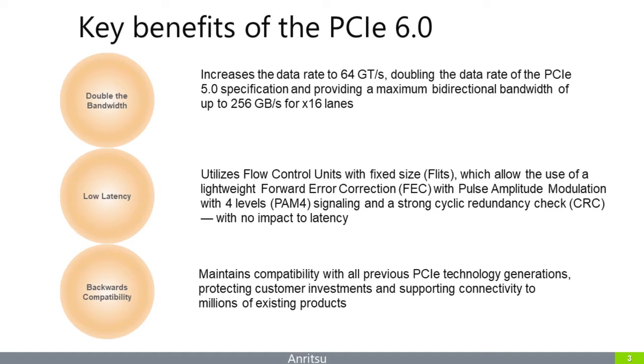Compared to the Reed-Solomon of IEEE for error correction, it's very light. I'm going to talk about the details later. And the last one is backward compatibility. In the last PCIe developers conference, there were a lot of questions about backward compatibility when we use, like, optical cable or jumper cable for new technology, PCIe Gen 6, Gen 7. But board members kept saying backward compatibility is very, very important.